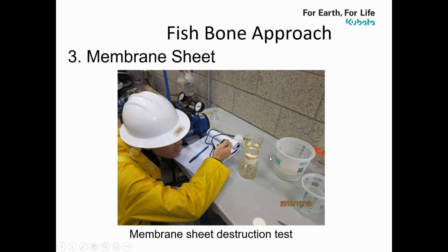Now, if sodium hypochlorite doesn't recover very well, then we could try an acid cleaning after sodium hypochlorite and see how much that will recover. We could also do it the other way around. We could do an acid dip first, and then a sodium hypochlorite clean next, if just sodium hypochlorite is not cleaning your membrane.